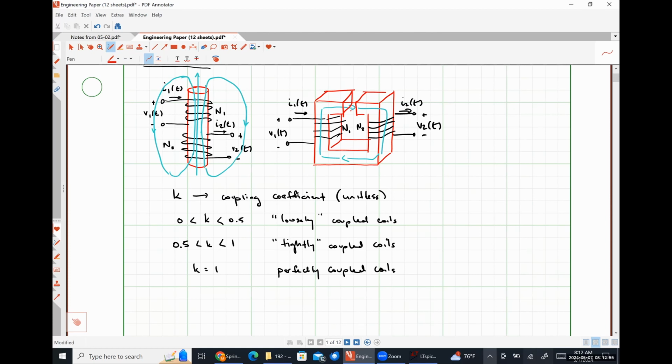So it takes energy in order to align the magnetic domains of high permeability materials. Some of that is going to manifest itself as heat. Some of that is effectively going to be like residual stored energy in the system, which is how we get permanent magnets and all of that kind of good stuff. So there are several different loss mechanisms that we are going to talk about in our later classes in great detail.